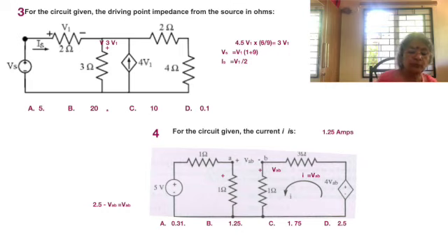Now let's move to the left hand loop, wherein we see a DC source having a potential divider out of 1 and 1 ohm. The voltage divides into 2 because both resistors are equal. So we have 2.5 volts across the 1 ohm standing vertically, such that the A terminal is positive and it is equal to 2.5. Now we have all the voltages connecting between B and A.